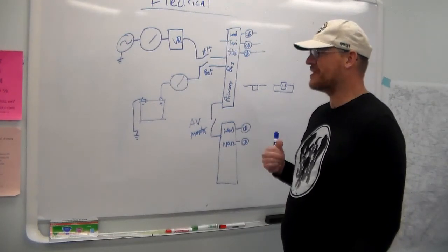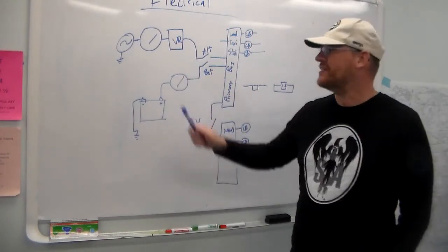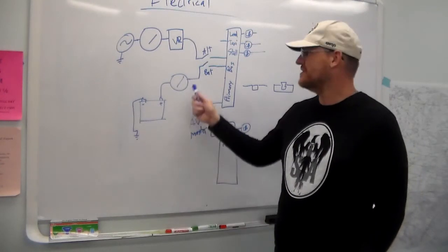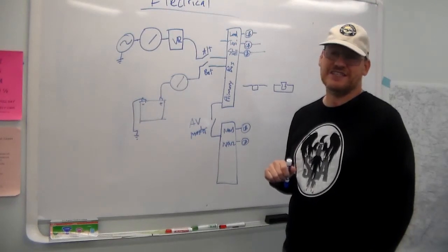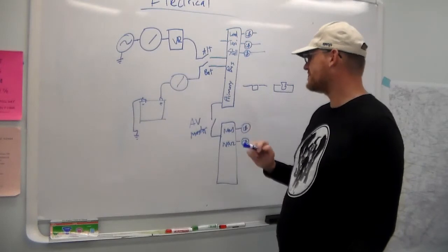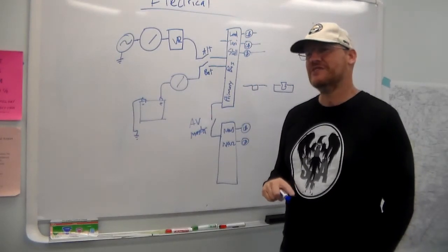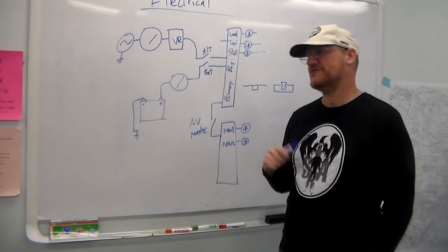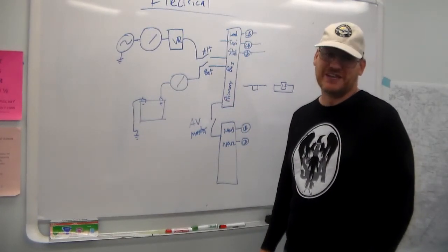So again, to summarize, when things go wrong, if this trips and suddenly you're not getting anything out of the alternator, try to reset that side of the master and see if it works. That's usually somewhat safe to do. And if a breaker trips, if it's an essential item, you can try it one time, and if it trips again, you're done. Figure it out on the ground with a mechanic.